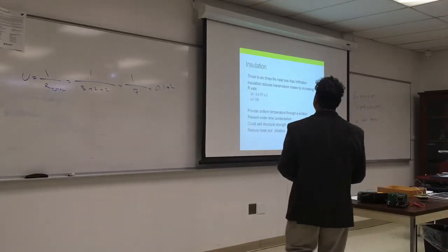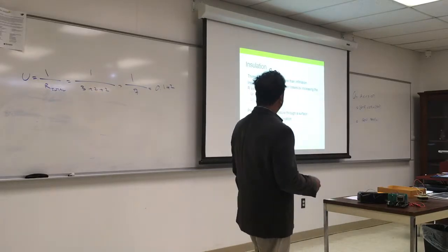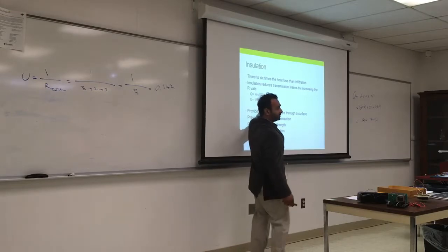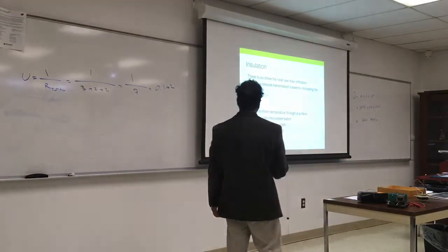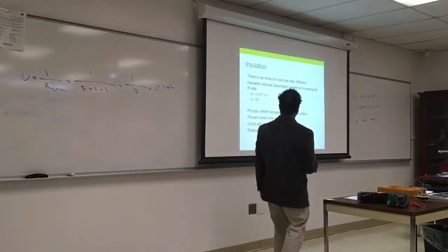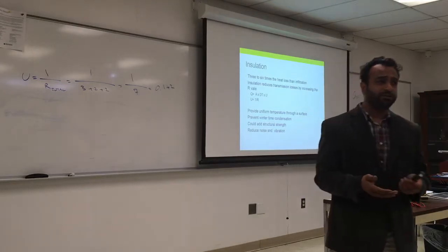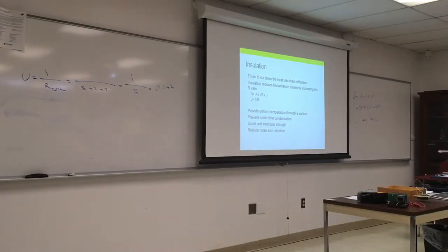So we talked about heat loss, and insulation has to do with the U factor. We know how to calculate that from the resistance over here. Transmission loss is 3 to 6 times the heat loss of infiltration. So if you have an infiltration loss of 30%, probably this is more through the wall. And if you touch the inside of the wall in the winter and it's cold, that means you do not have really good insulation.